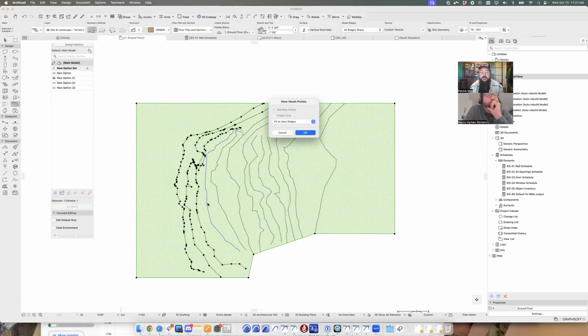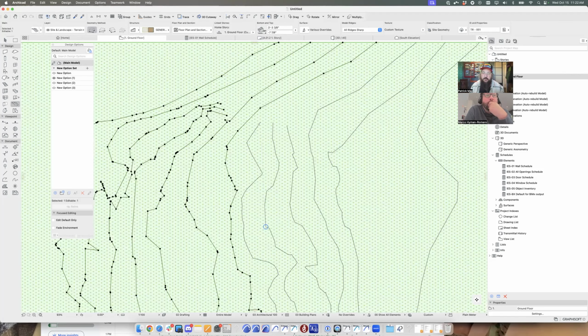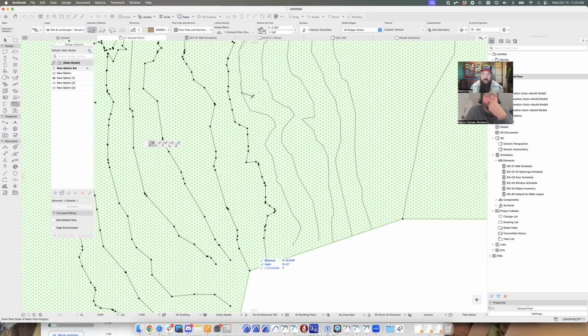Being systematic, I'm going to apply all of these contours in one sweep. Now, let's say I had a relatively flat site with maybe only 10 or 15 contours. If they're relatively simple, you can technically, with the same criteria, select the mesh tool and polygon method, and click directly onto the site mesh and start applying contours.